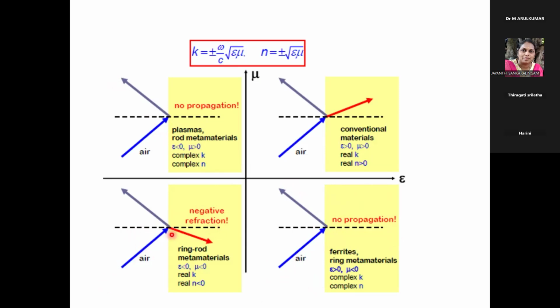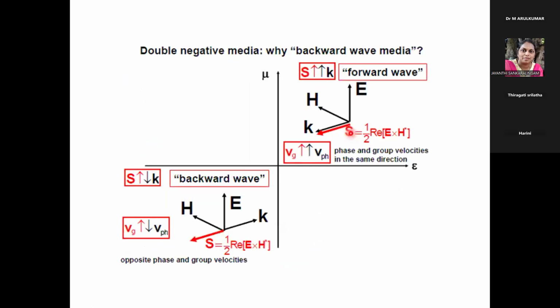if the wave is incident, it will get reflected partially and it will get transmitted. But what is happening is the direction of transmission is changing. So this is the unique nature of this material, by which you are going to get some other properties which are not possessed by the dielectric material. So that's why this material which is having epsilon negative and mu negative is called a metamaterial, and it is used for many applications, which we'll discuss later.